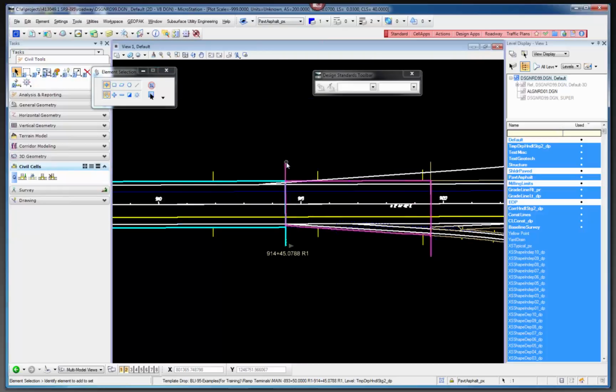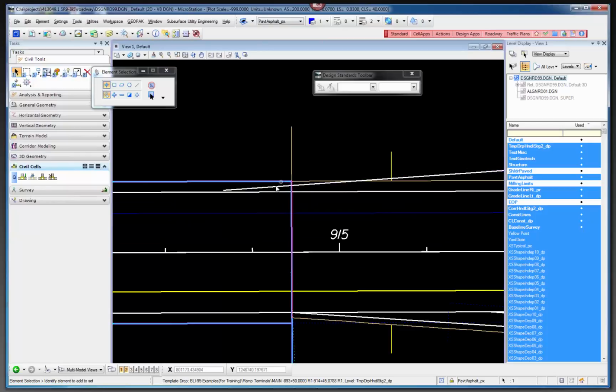I have one template that basically goes across both roadways, northbound and southbound here on this 95 interchange, but I probably would design them separately and just have a median that transitions, because these things could stagger, and you would end up building yourself way too many composite templates. So it's sometimes easier just to build templates by roadways and then work out the details in the median.